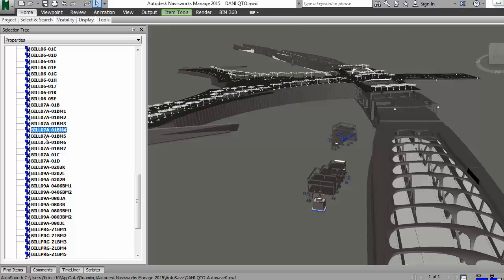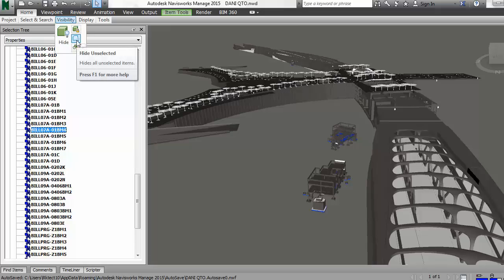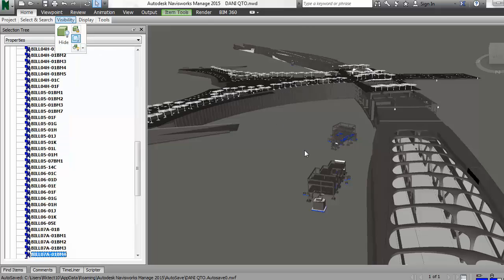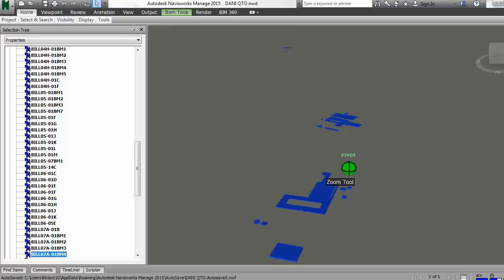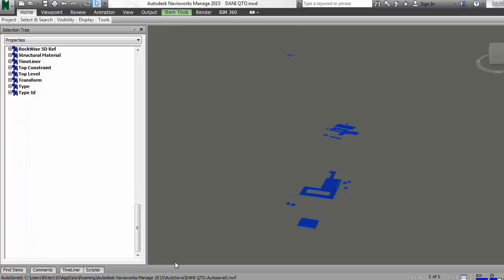Finally, it is important to note that you can use the reporting tools of the 3D viewer to sort and filter the integrated 5D contract information. Here, we can select any map contract item code, and the viewer shows directly the concerned elements that are mapped to this code in their different locations. Hiding or unhiding and other conditional viewing and filtration becomes a very easy and fast procedure. Real 5D data transforms virtual design modeling to real site and contract situation.